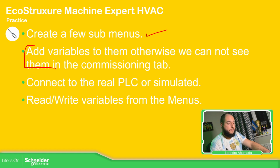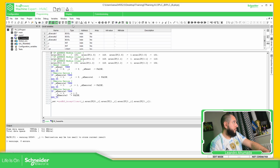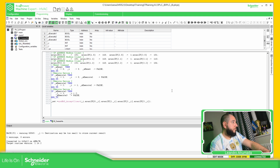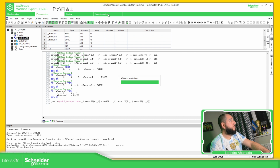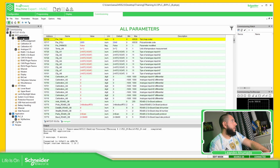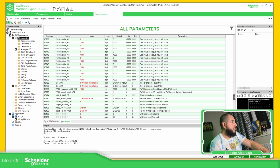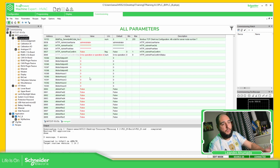So let's do that. So let's connect to the controller now. Yes, I want to download this. Now, commissioning. If you don't do that, you probably need to go here and check for the variables. Okay. In this case, I have a few variables and they're all just together. It's easy. But if you have more than 100, 200 variables, it's going to be a little bit complicated.